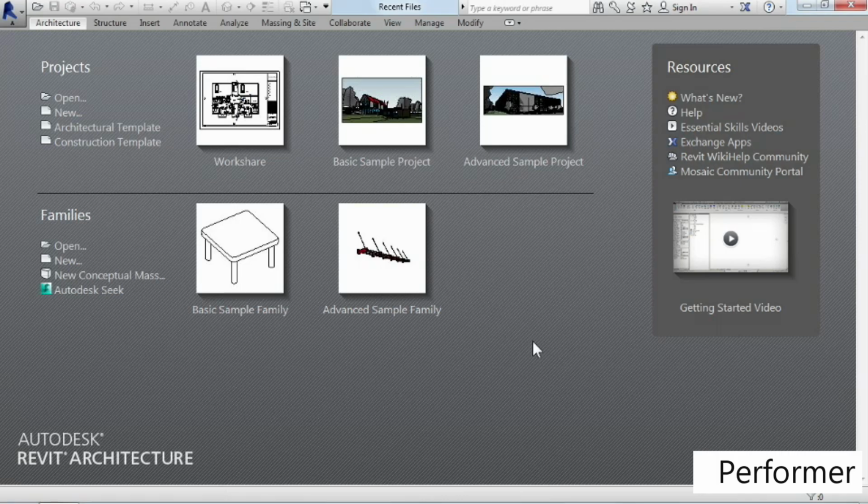In so doing, everybody is able to work together on a project team and all make changes to various parts of the project. Now, I should also mention that if you're using Revit LT, the work sharing feature is not available in Revit LT. So Revit LT was designed for single person offices, where 1 or 2 people work there and they're working on their own standalone projects. So if you're working with Revit LT, then you're basically going to follow the steps that we did in the previous movie to open a project.